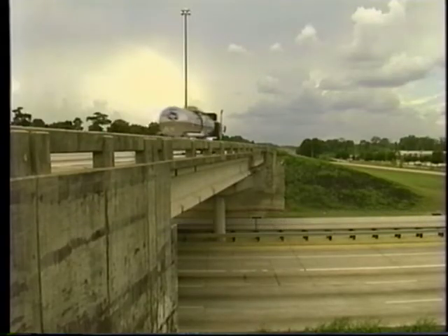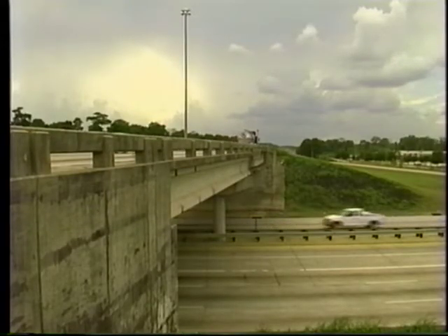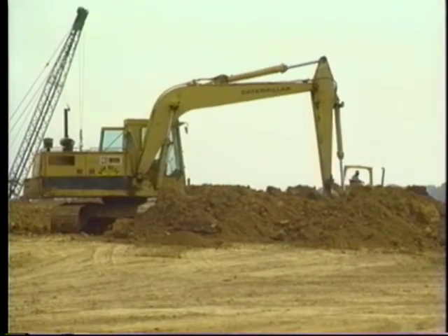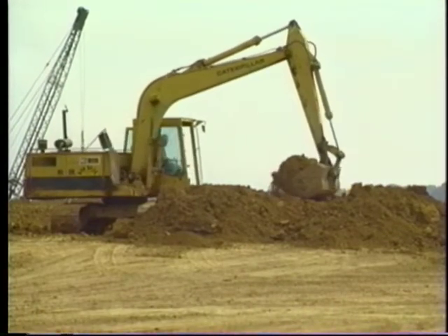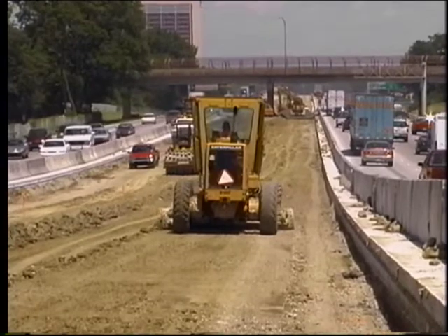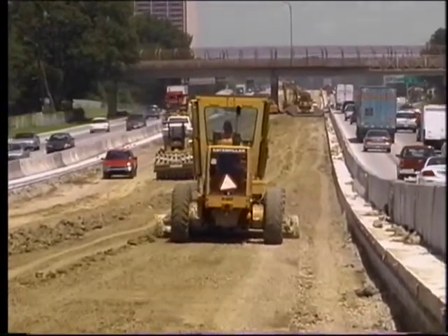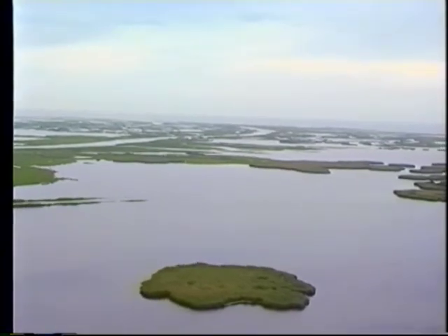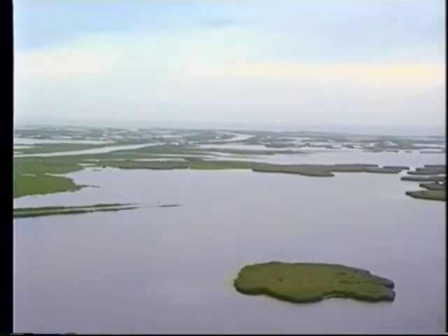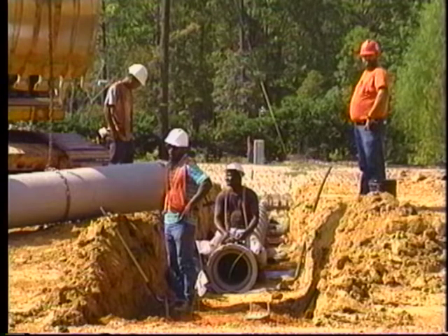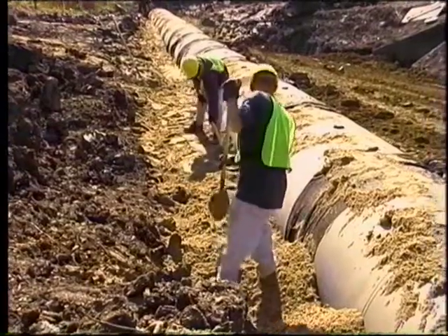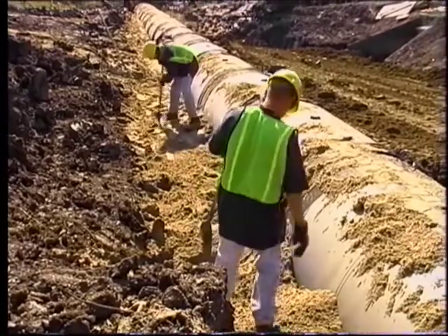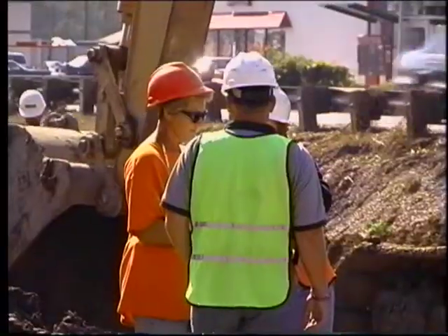Some examples of things that can cause erroneous test results are a trench wall, ditch, or adjacent structure, cars, trucks, or construction equipment near the testing site, a large body of water or high water table near the site, or too many people gathered around the device when it is working may affect moisture counts. Always be aware of your surroundings when you're about to perform a test.